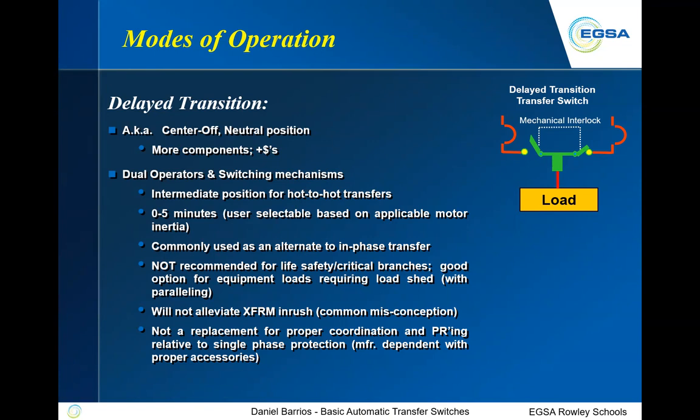In the case of skimmers or bubblers, typically in a water treatment plant, if it waits 30 seconds to a minute before it's re-energized, it typically is a safer transition and does not damage any of the equipment.